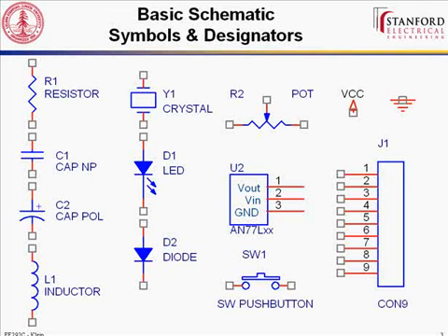In some simulators, in order to change the value of the crystal, you change components like the resistor, capacitor, and inductor, because the crystal can be modeled by those three components. Is it the same here, or can you just change whatever you want? Okay, so the question has to do with if you're using a simulator, do you need to model a crystal with other parts that are linear? And you do not. This is just schematic capture. This is what you actually want to create on the board. And on the board you're designing, you want to actually put a crystal in. So this isn't a simulator. This is just for the actual schematic.